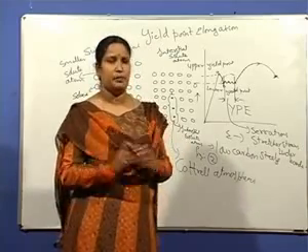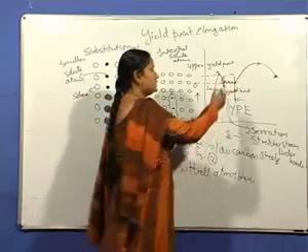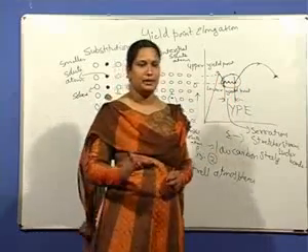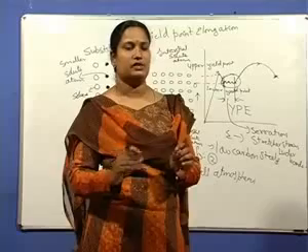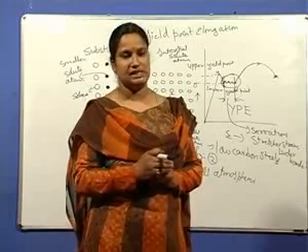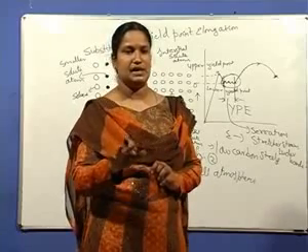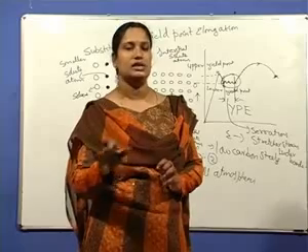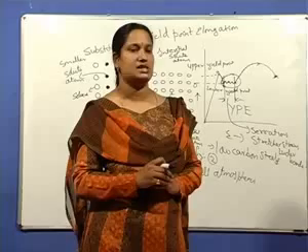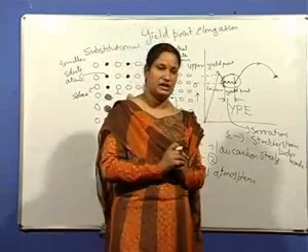During sheet forming operations, because of the presence of this yield point phenomena, it gives a very bad appearance on the surface of the sheet material during forming. The rough surface is seen, the Luder bands, the serrations appear very rough on the surface. That gives rise to very poor surface finish for low carbon steel sheet materials.